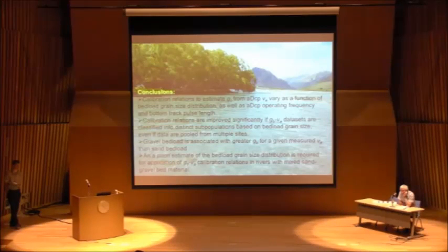and our belief is now that when it comes to a bigger flood and we have bed forms like we observed at the Danube, gravel dunes, which we have just worked on, at a speed of 5.9 meters per hour. They are 11 meters long, 30 centimeters high, and they move at almost 6 meters per hour. And when they are 30 centimeters high, the total signal, the vibration of the geophone steel plate, doesn't work anymore. So unfortunately, I must say, due to our experience, that in alpine rivers down to the big Danube River,